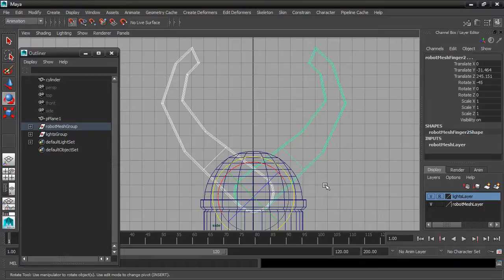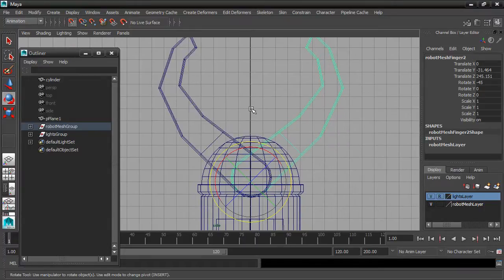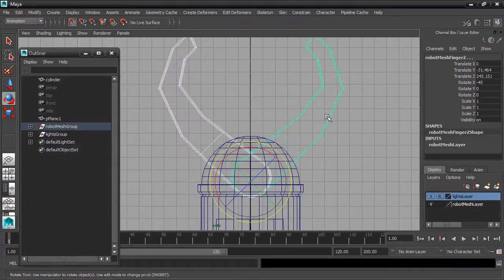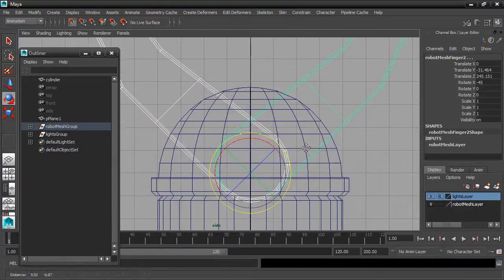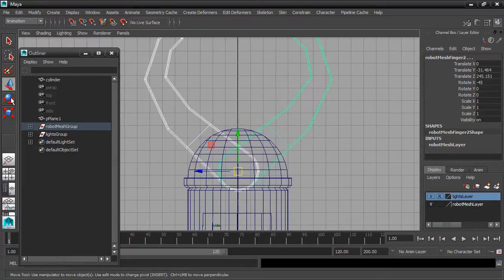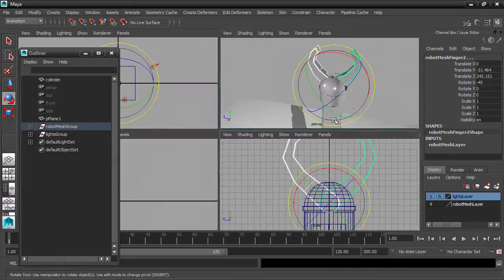And then release the mouse. And you'll see, if I select either one of them, the rotate gizmo is located here. Very good. I'm going to select them both again. And just fine-tune that pivot location without the grid. Snapping off, use the Move tool, and hold down D. Just pull that up a little bit until it's centered. Then test the rotations. You can just grab the Rotate tool and rotate them both at once, in fact.